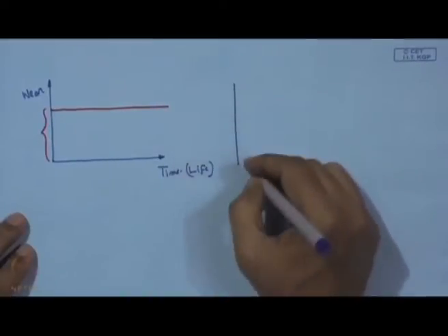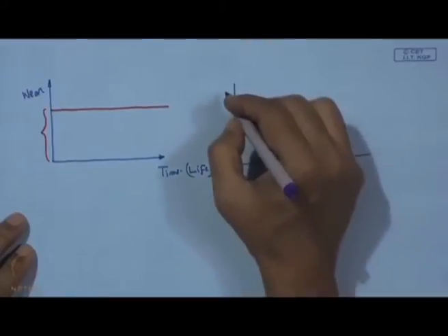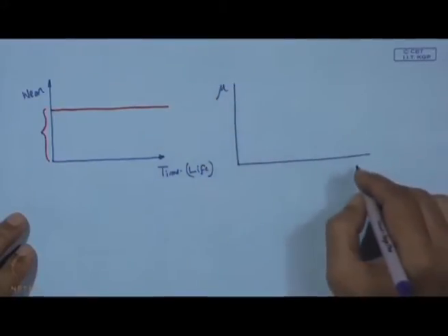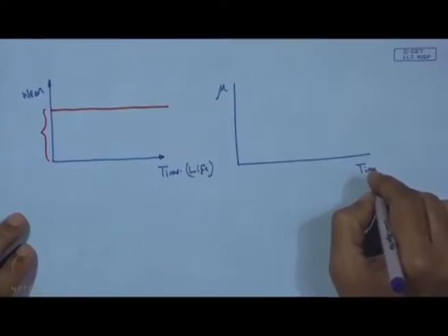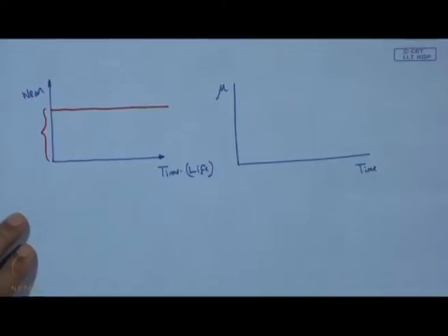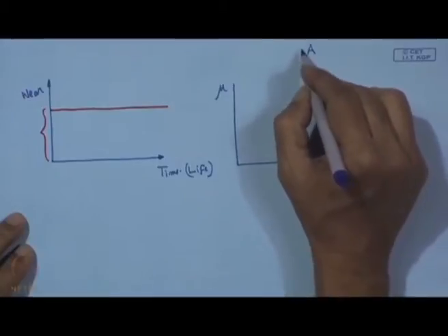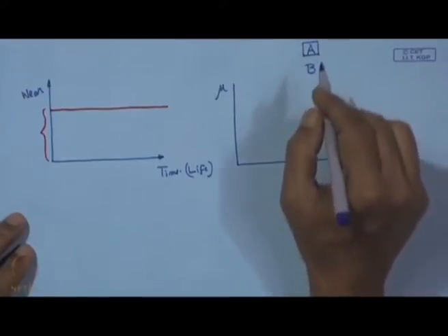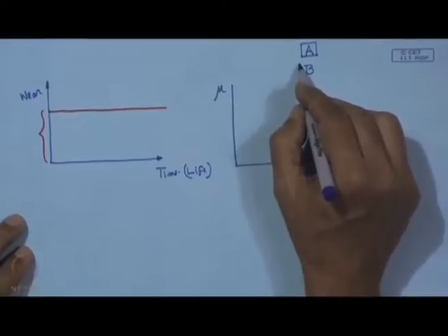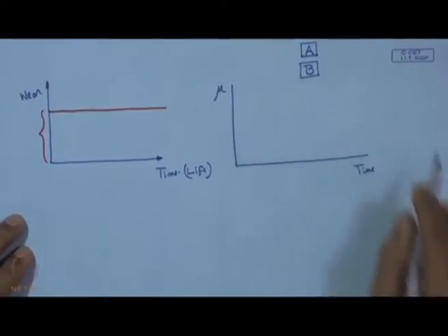And here this limit is given on wear, and at the same time what is also important to understand is this friction, or say coefficient of friction, and this is also against time. So, when we have two elements of a pair, say A is in contact with B, that means this is one component of the tribo pair and that is B. So, A and B, it may be screw nut, it can be cam follower, it can be two gears, it can be the surface of the cutting tool and the chip.